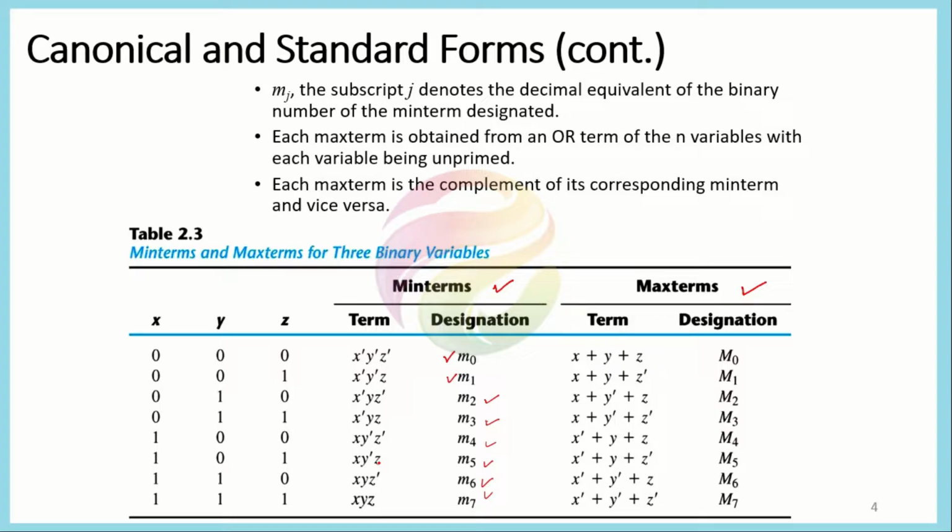In a min term, it is a must that you mention all the variables here, because you cannot write x complement y only or xy complement only in the min term. You need to represent the z term too. So in the min terms, all three inputs are included in the representation. If the corresponding variable has the value 0, then it is represented by its complement, like x complement, and if the corresponding value is 1, then it is represented by the variable itself, say x. Now, in a similar manner, we will represent the max term.